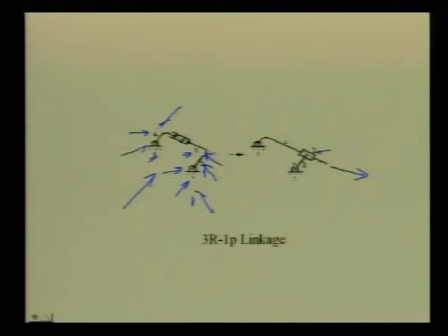So, it has 2 kinematic dimensions, namely the length of this link, let me call it L2, and the distance between these 2 revolute pairs located on link number 1, which we may call L1. So, L1 and L2 are the only 2 relevant geometric dimensions, and the direction of this prismatic pair, which is parallel to this direction, that is important, and that has been written. This is what we call a kinematic dimension of the original mechanism.